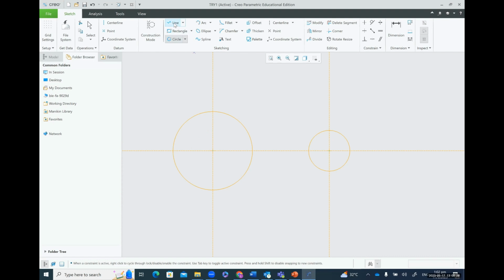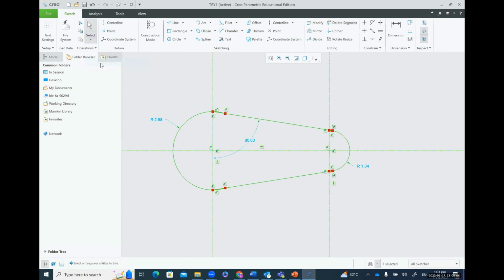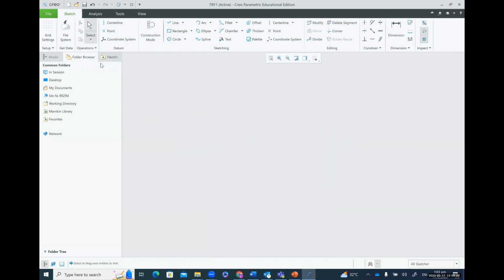Now you can add a line and connect this. Okay. Press escape key and connect here. Press escape key. Okay. Now, of course, you can delete the segments that you don't want. For example, here, left click, you want to delete these segments which you don't want. Okay. So this is a two-dimensional sketch with a combination of lines and the circle. Okay. So we want to delete it all. Select all geometry, press the delete key.